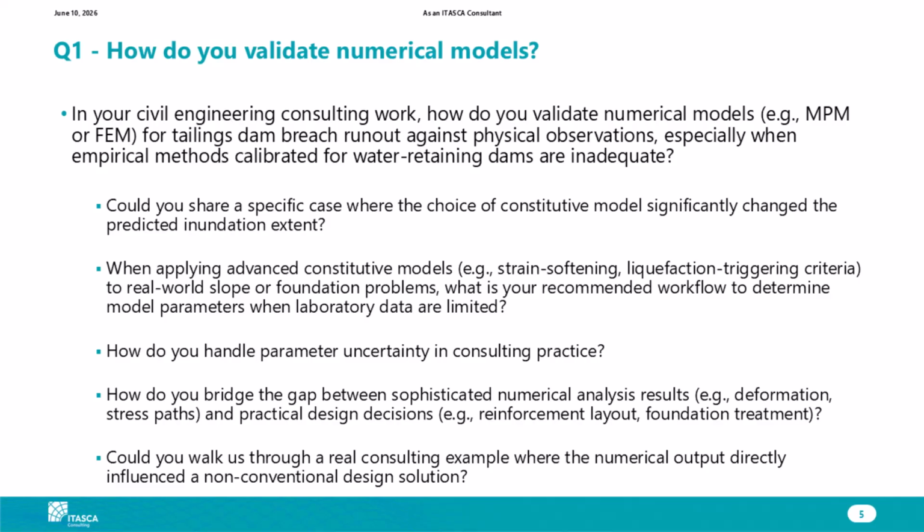Even the old SPT, for example, when CPTs are not available because you have a stiff granular soil, can on its own provide a good hint in terms of soil variability and in terms of distribution of properties around the site. Then you can plug in some sensitivity analysis in terms of what you correlate to the SPT, in terms of Vs, for example, or friction angle and whatnot.